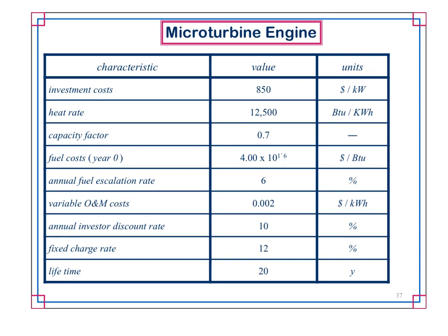Because you have a fuel source, you don't rely on the wind or the sun to provide your energy source. So you have a pretty good capacity factor. You do have to do some maintenance, but not too much. Also, you might want to have your microturbine oversized for the load so that depending on how the load varies, you might be able to pick up additional load.